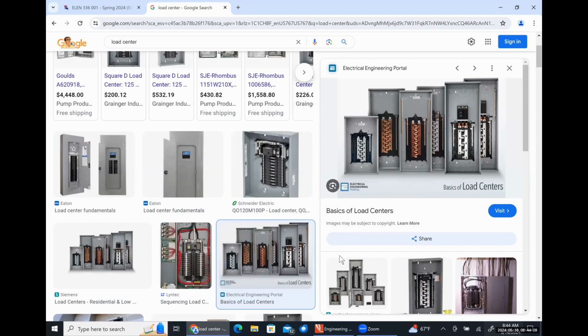So it's going to try to draw as much as it can based on the system that it's connected to. HVAC units, similar kind of thing. The compressor is going to run a little bit differently because it's getting 208 versus 240, but in the grand scheme of things, it doesn't make that huge of a difference. So different regions of the world design their electronics slightly differently because they have to worry about changes in frequency. Here in the US, we use 60 hertz. There are other countries that use 60 hertz. I think Australia does, but I'm not 100% sure on that. Most of Europe uses 50 hertz. So there are lots of little considerations.